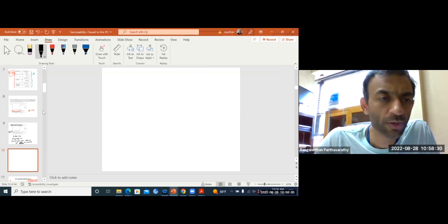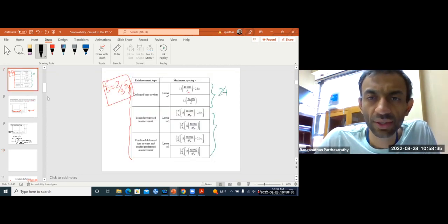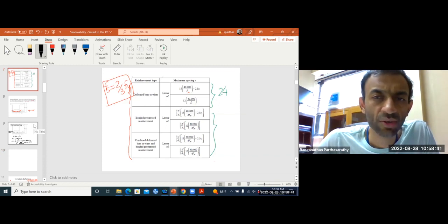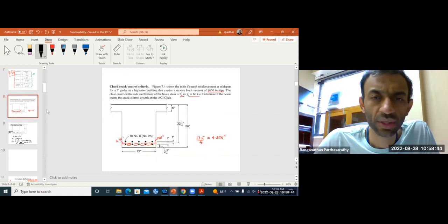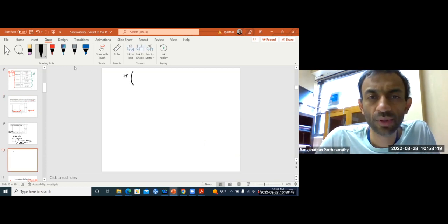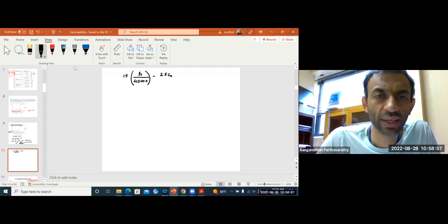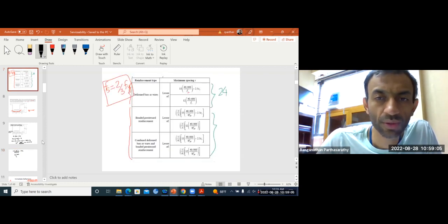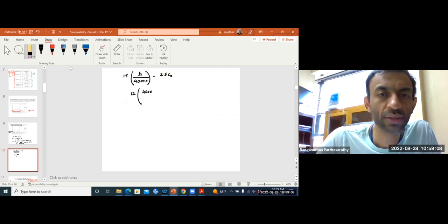So now let's go back and check our criteria: lesser of 15 times 40,000 by Fs minus 2.5 times clear cover. So that is your first criterion. Second one is 12 times 40,000 by Fs.